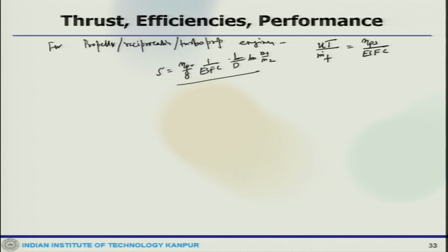Obviously, if you look at this expression, to maximize the range, the lift to drag ratio and the propeller efficiency are also to be maximized.